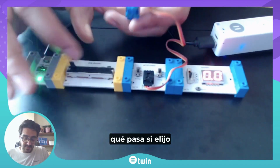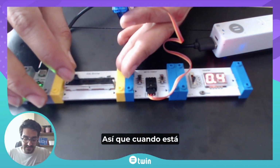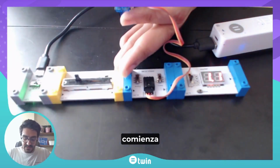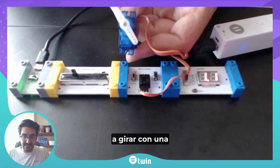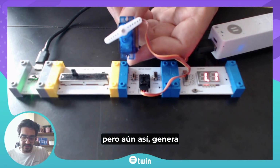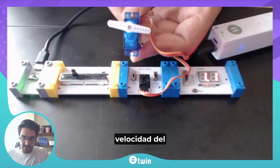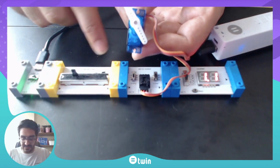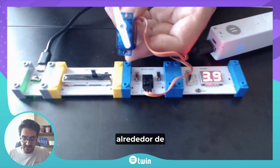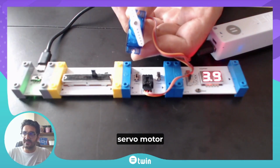And let's check what happens if I choose the sweep mode and then change the value. When it is at around 1 volt, let's say, it starts to rotate at a lower speed, not full speed, but you still have the sweep motion. So you can adjust the speed of the servo motor by using different inputs. If there is a higher voltage, let's say around 4 volts, you can see the increase in the servo motor's speed.